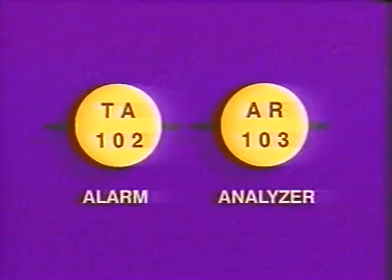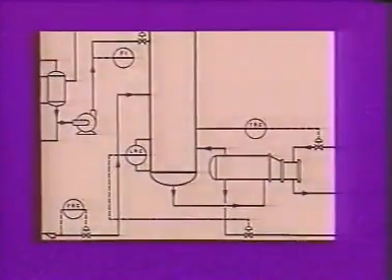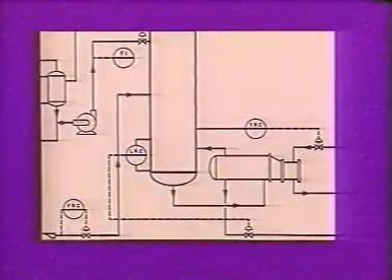Process piping and the walls of process vessels are usually shown as solid, unbroken lines. The lines supplying air to process instruments are shown by short diagonal marks crossing a solid line. Here, a valve is connected to a controller by an air line.